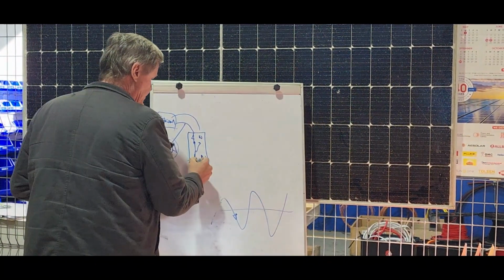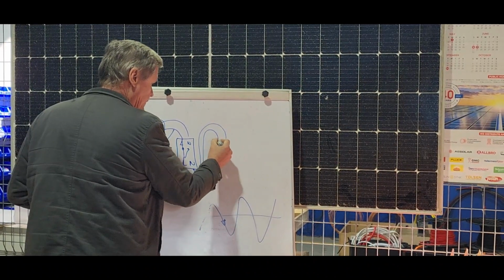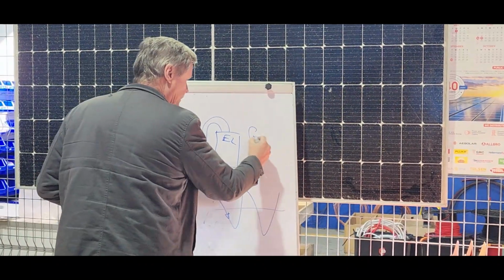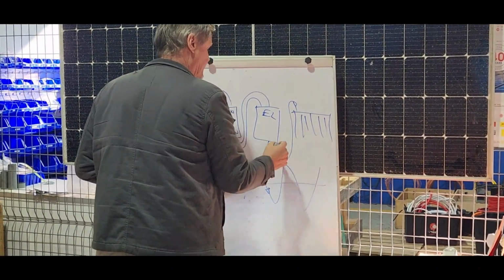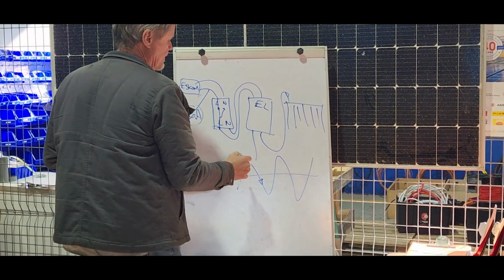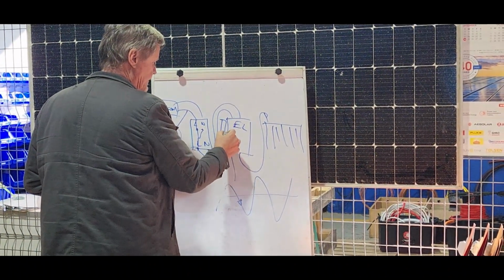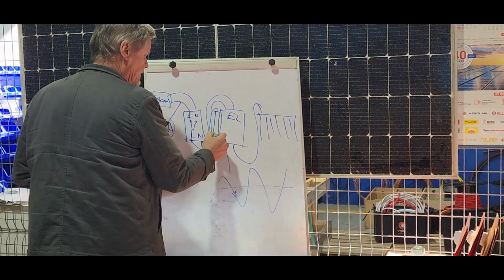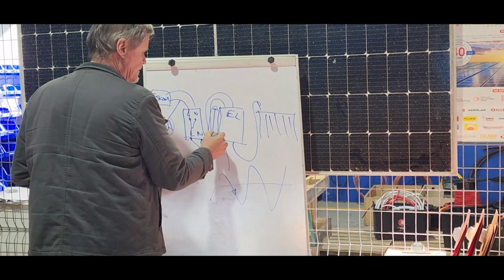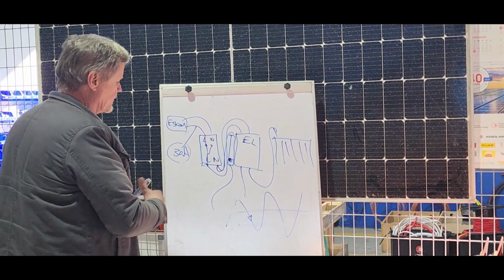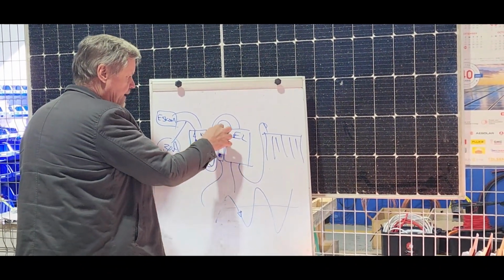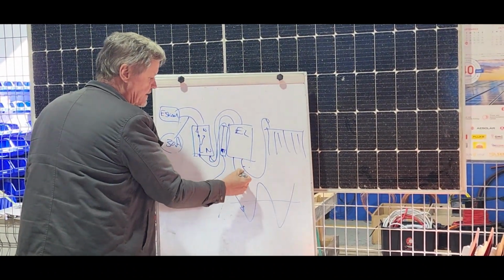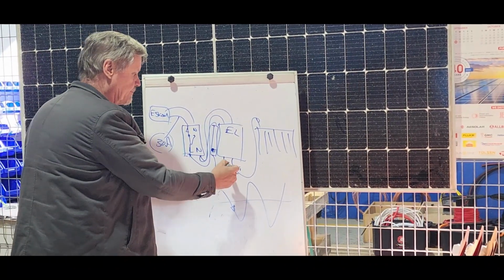If that is on my main switch, and that feeds my earth leakage, and my earth leakage feeds all my other breakers. But I also have a breaker over here that is not on the earth leakage. Let's say that is the stove. So we've got two cables coming out. The one cable goes to the stove, the other cable goes to the earth leakage. Can I put my CT around this cable? Well, I can, but should I?